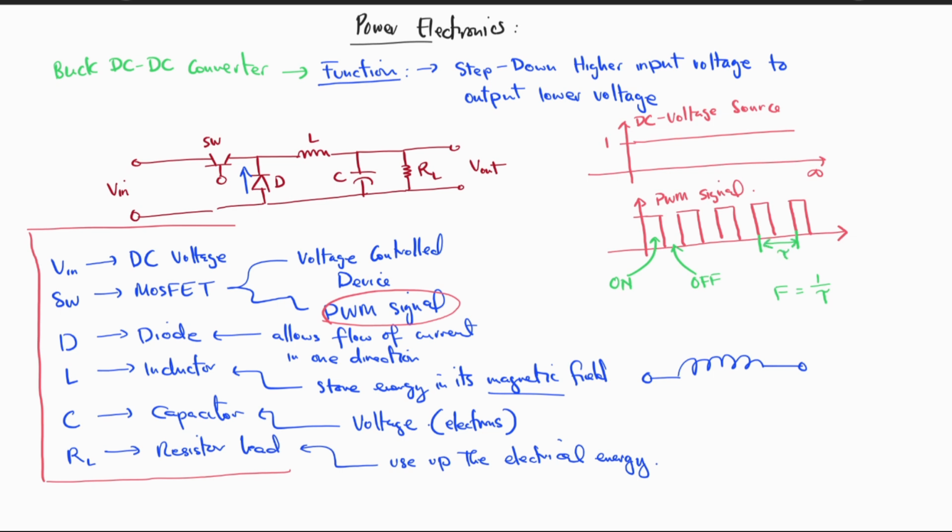And there is a difference between the period and the turn off and turn on cycle of the PWM signal. This can be T on and this can be T off, where the turn on is the period of the switching on of the PWM signal, having the value of 1, 0, 1, 0, 1, 0 and so on. And the turn off time represents the period in which the signal is switched off, which is represented by the 0.